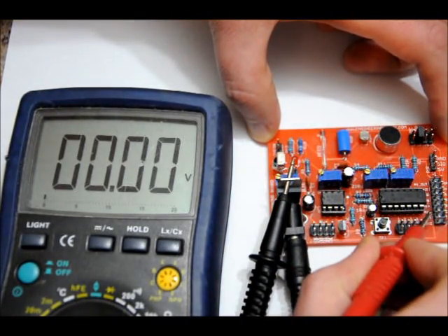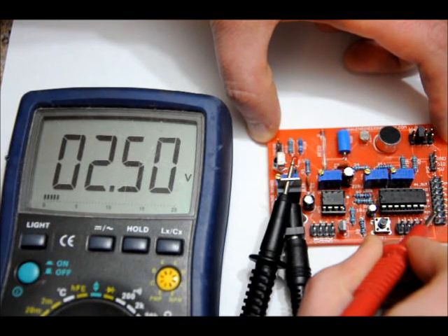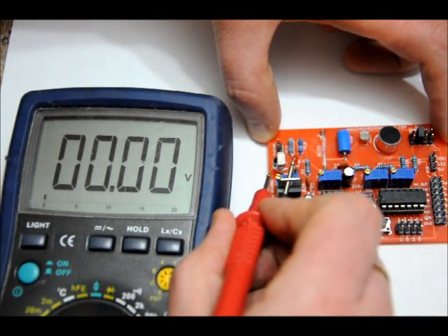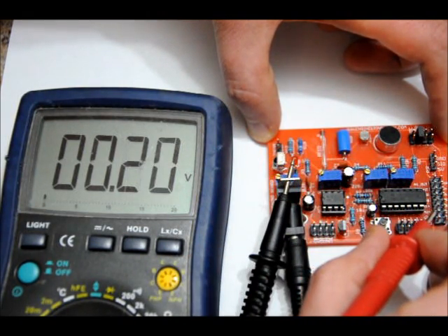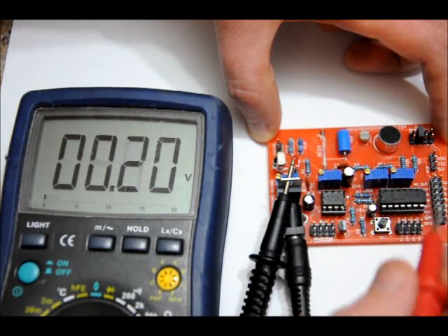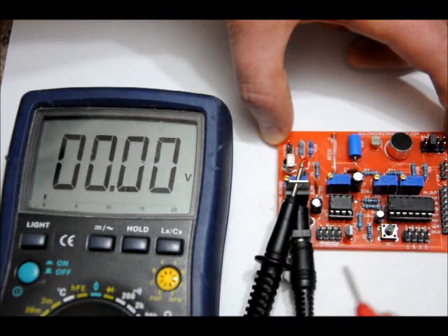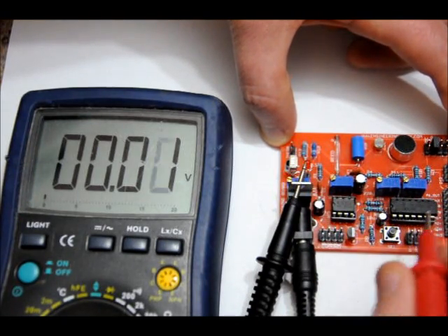So to tune the VAR pin, we want to tune that to 3 volts. Right now it's sitting at 2.5 volts. All I have to do is turn the VAR variable resistor right a few times, and I'll get that close to 3 volts. We did that in video 1. We tuned that variable resistor, so if you need to look back, please feel free.